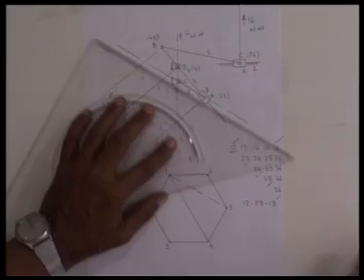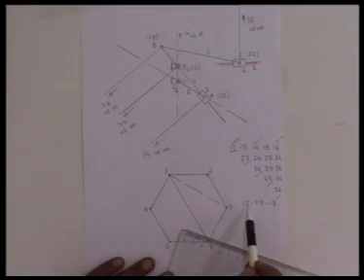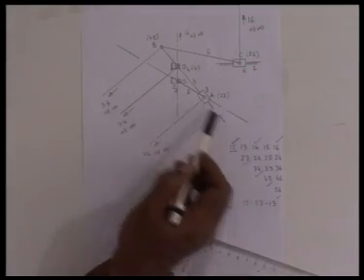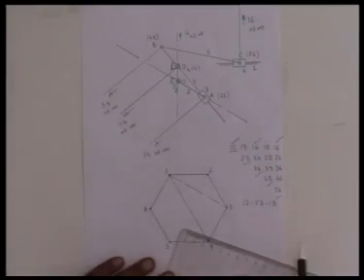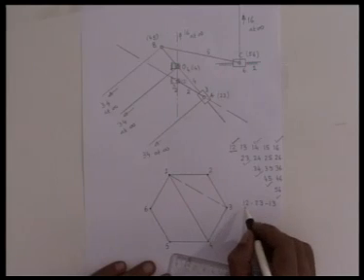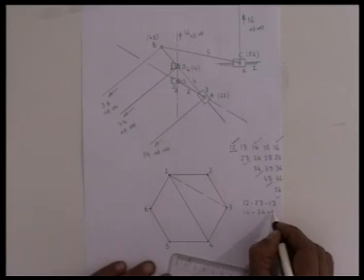This is what we call the Aronhold-Kennedy theorem, that 1, 2, 2, 3, 1, 3 are collinear. 1, 2 is here, 2, 3 is there. So, 1, 3 must lie on this line. And 1, 3 is this diagonal, as I see 1, 4 and 3, 4. So, I consider 1, 4, 3, 4 and 1, 3.